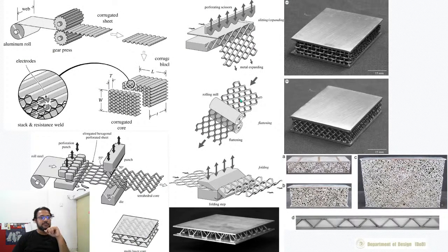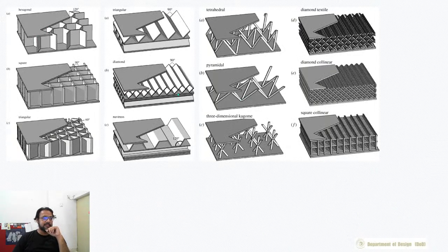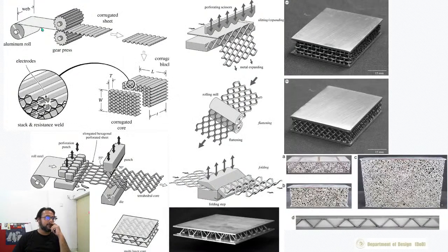I think I have one. So how would you create something like, let's say, this piece over here? It's very interesting. You have an aluminum sheet metal which is passed through rollers, and you get these kind of corrugated shapes. When you join it together, you could weld it at certain positions. You get this honeycomb structure. You cut a piece of it and place it between two sheets of material, and that becomes your honeycomb structure, and that is very, very light and really, really strong. You could make this out of paper, and you would realize how strong such a material configuration is.